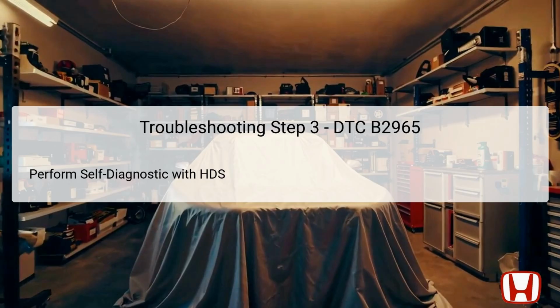Following the ignition reset, the next step is to perform a self-diagnostic function with the Honda Diagnostic System, HDS. This step assesses whether the previous DTC B2965 reappears and evaluates the overall condition of the rear AC control unit and the HVAC control unit.